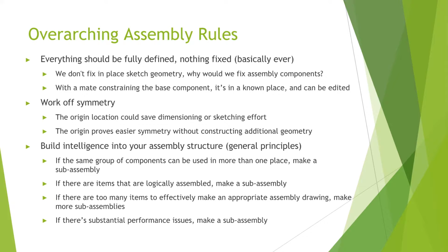And then there's a point of diminishing returns, but there are substantial performance gains to be had making subassemblies. The reason is that every single live mate that SolidWorks has to calculate is a performance drain. In a subassembly, SolidWorks calculates, let's say, 100 live mates, which would be roughly 33 parts. Once those are calculated, that subassembly is a blob that goes into a parent level assembly. That blob only then needs 3 mates to constrain it. So you've got your chain of mate dependencies, and at every level, SolidWorks is going to calculate the mates once, and then a second time if a change is made.